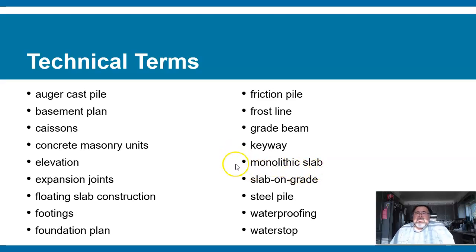A monolithic slab. It's just saying it's a slab that's made out of one. It's one slab made out of one piece and one pour. So it might be a slab that includes walls or raised areas where walls might rest around the exterior, even in the interior of the building. And it has footings or stem walls above it and maybe footings laid underneath.